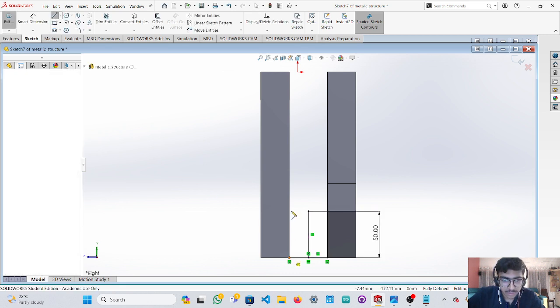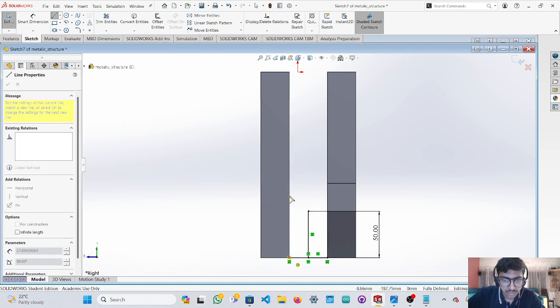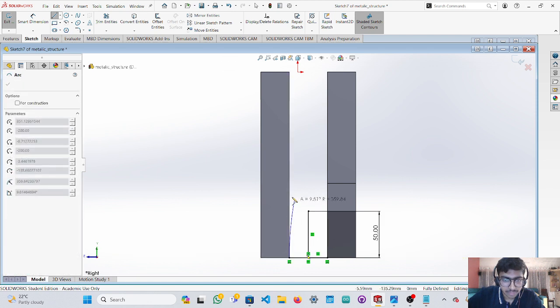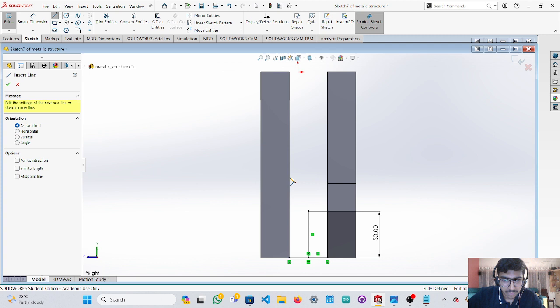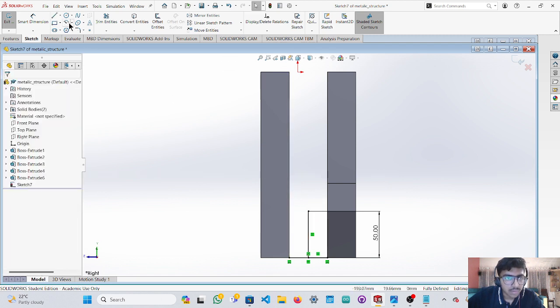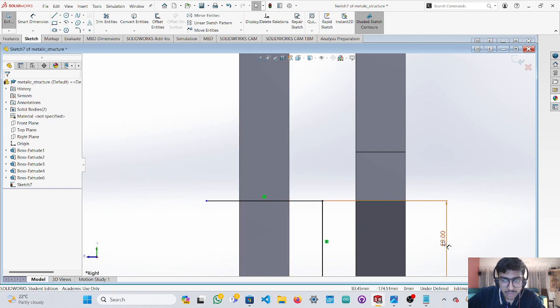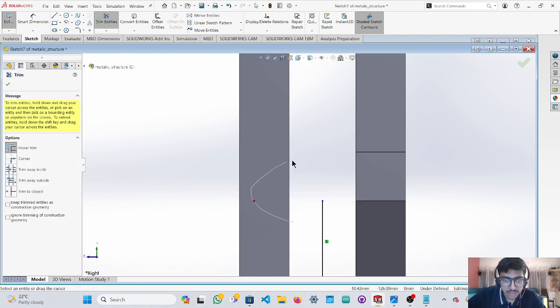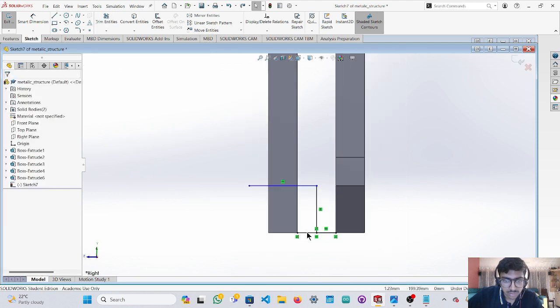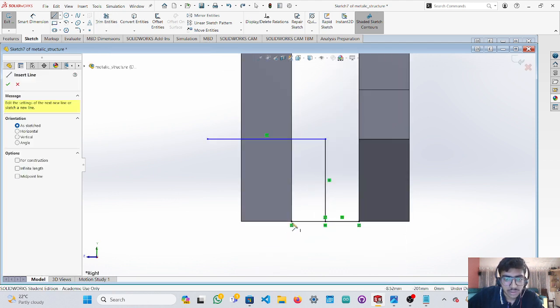Now we take this part, go all the way up. Let's extend this part. Delete this. Trim entities. Now we just draw a line from here.